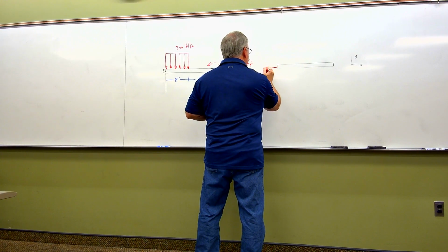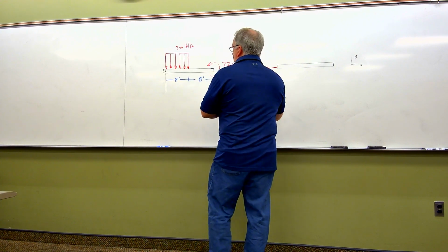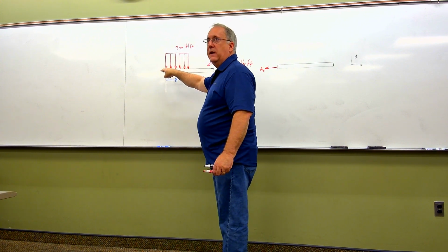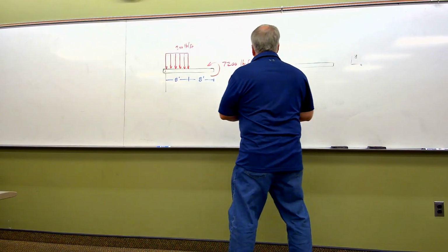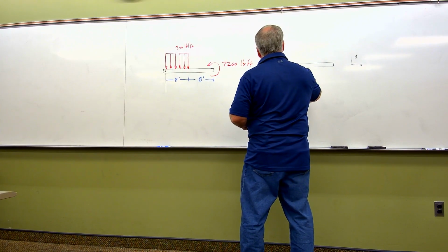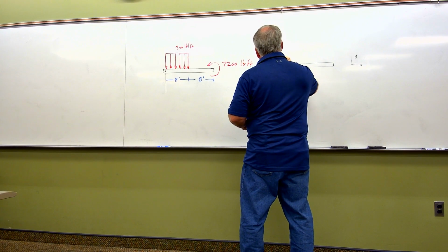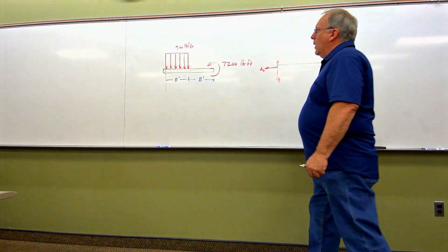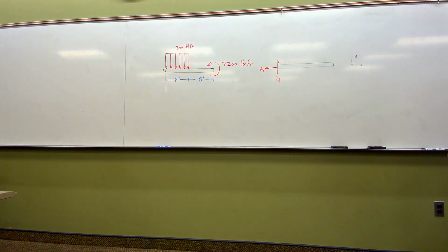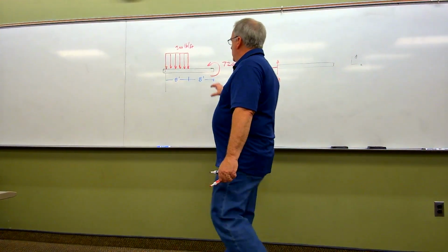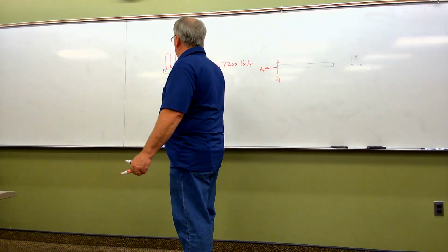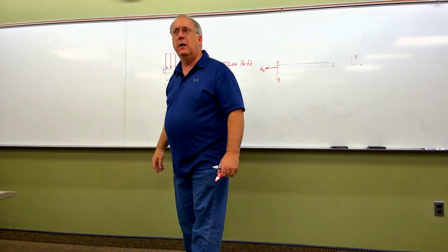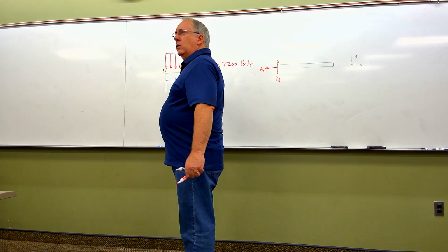Let's assume that that's force AX. If you try to move this beam up and down in the Y direction, will you face resistance to motion? Yup. So there's going to be some sort of an AY associated with that. Let's call it AY right here. Now, also very importantly, if you tried to rotate this real life beam around point A right here, with that thing solidly locked in, would you face resistance to rotation?